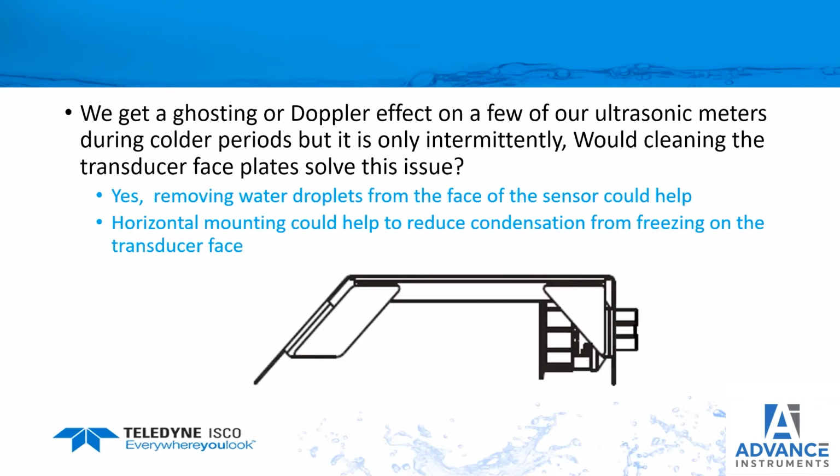All right, now that it's colder out, I've had several questions coming in about cold weather, and this person was having problems with ghosting with their ultrasonic sensor when it's cold out. They were asking about cleaning the face of it. So yes, cleaning the water droplets off the face of the sensor could help. If it's mounted in a vertical orientation with colder weather, sometimes we get steam coming up. You get water droplets developing on the face of the ultrasonic transducer. The water droplets can freeze, and then that could cause some problems.